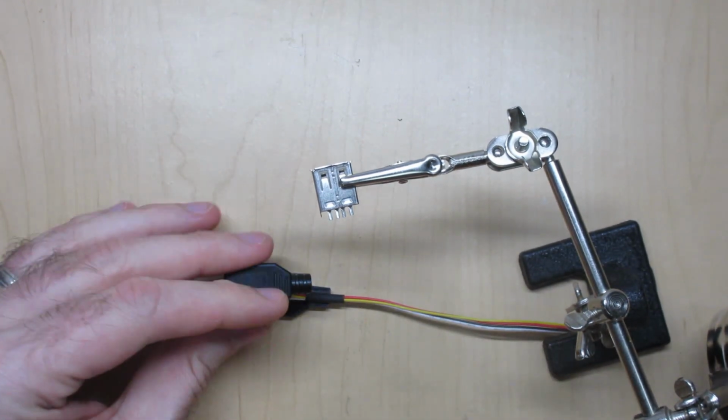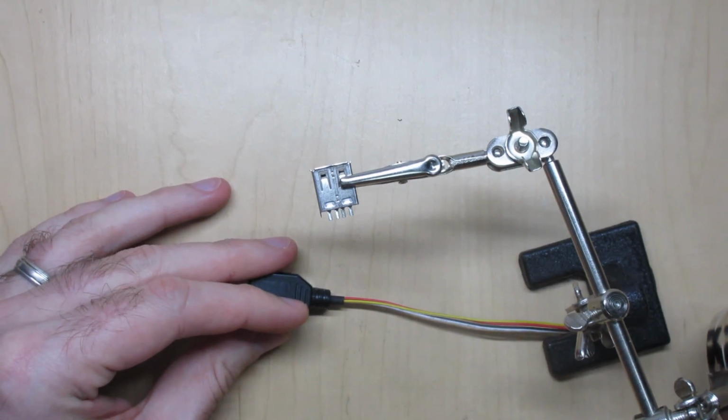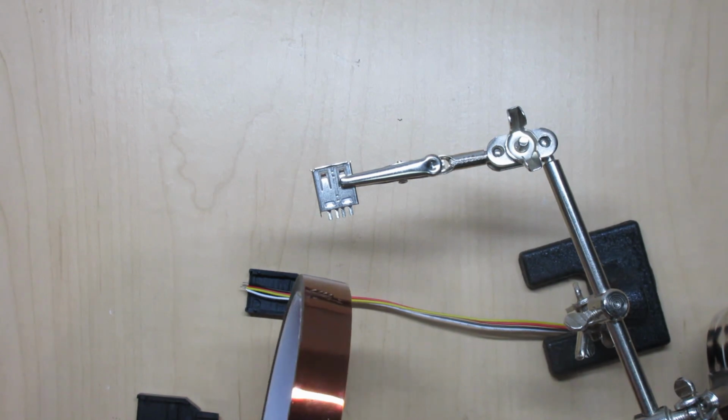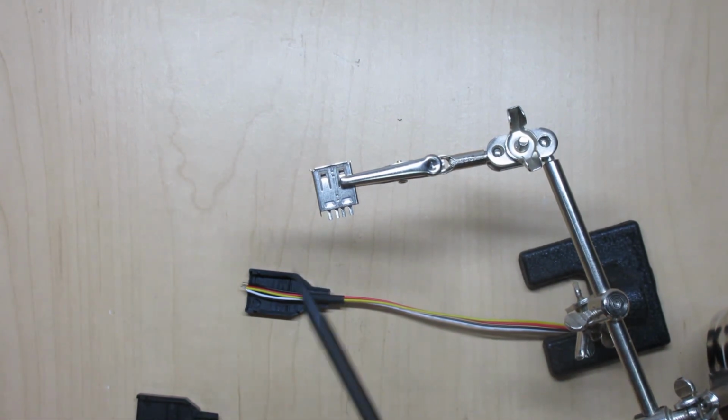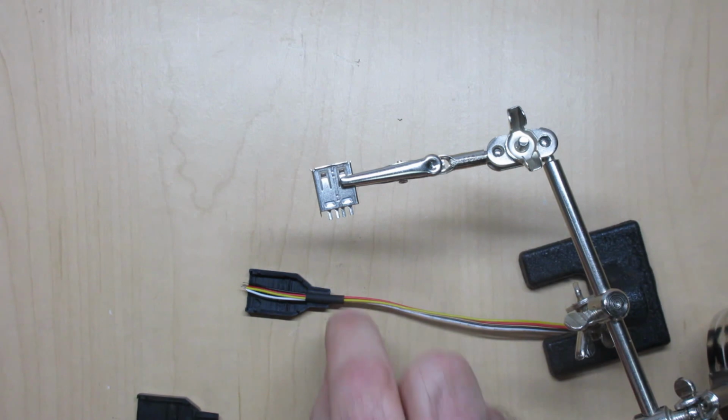And so when this closes, the wires will be kind of bunched together and they won't be easily tugged out of position. And then finally, I'm going to use a bit of Kapton tape to seal the terminals around the wires once everything is soldered in place. That's not foolproof, but it should provide a little bit of protection against somebody tugging on the end of it unnecessarily. So let's go ahead and get this thing soldered together.